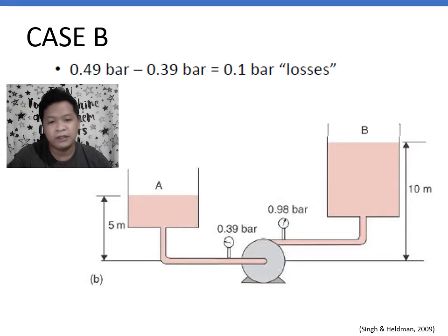However, if we look at the area here, the pressure reading is lower than in case A, which means that there are frictional losses that have been accounted for. So in real life situations, as you mentioned, there is friction in the elbow, friction along the length of the pipe, friction when the opening constricts or enlarges. And sometimes the equipment itself has friction factors and contributions.